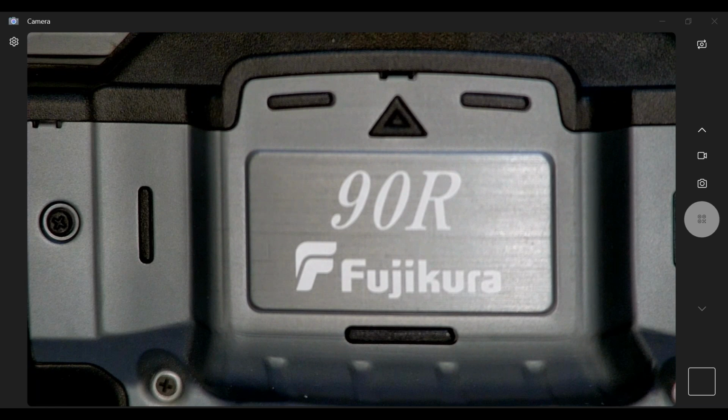Okay, that is awesome. Thank you. So we did get that it is a 200 core and a 250 core diameter. For that, I would say please use a pitch conversion fiber holder. So basically you can convert the 200 to 250 and you can use the same V groove, the 250 V groove, and complete the splicing. So that will not be a problem.